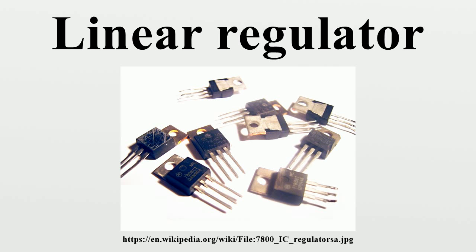Overview. The transistor is used as one half of a potential divider to establish the regulated output voltage. The output voltage is compared to a reference voltage to produce a control signal to the transistor which will drive its gate or base. With negative feedback and good choice of compensation, the output voltage is kept reasonably constant.